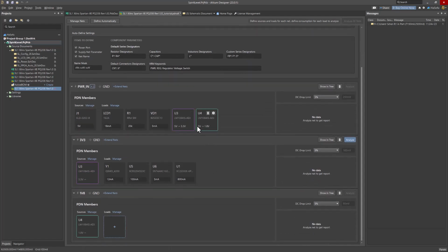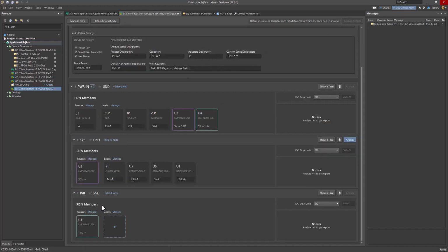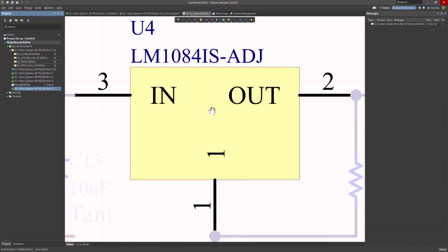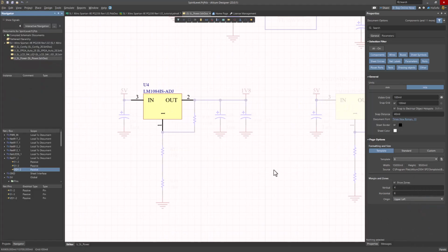This load is a VRM, another child of the parent. This is the parent. This is the voltage regulator module presenting another power child of the parent. And its load is the 1.8 volt section of the FPGA, which is U1. So its load, let me just double check to make sure. You can go to your panels, navigator.